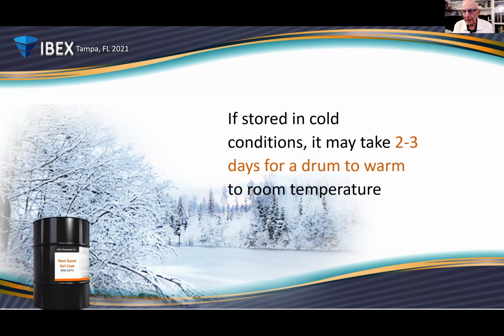And it's not a matter of the temperature of the gel coat on the mold. The temperature of the gel coat on the mold is very quickly going to become mold temperature, but it's a matter of getting it out of the spray gun, trying to spray this high viscosity material, and ensuring that the initiator mix is appropriate, and so on and so forth. So the pros and cons: stored in cold weather, the shelf life is longer and the material will be more stable. However, you have to make sure that you bring it up to room temperature before you spray.